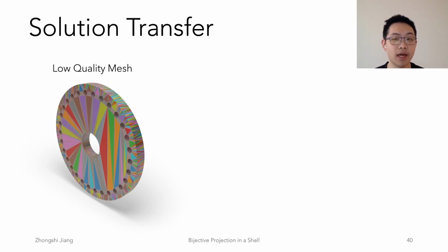Starting from a triangle mesh with many slivers, different triangles here are indicated by different colors. We would like to test the elastic response by stretching these two ends. However, the quality of triangles would give a hard time for conforming tetrahedral meshing and subsequent volumetric finite element simulation. Instead, we build a shell.